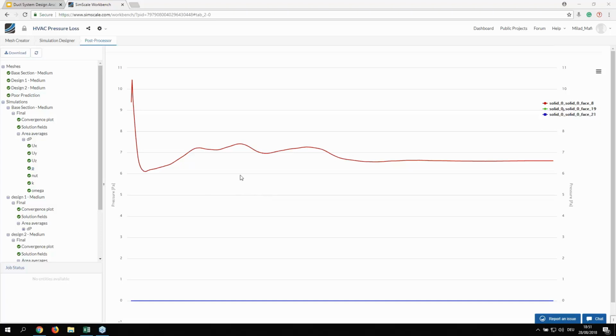Scott wants to know how the scale of the system influences the accuracy of the simulation, and that's a very good question. Actually, that's a great thing about fluid flow simulation. You still have this Reynolds number phenomenon, so it allows us to compare different cases which are identical from a geometrical point of view but have a different scale. But in general, I would say the scale does not make a big difference. It's just, in the end, a question of units.